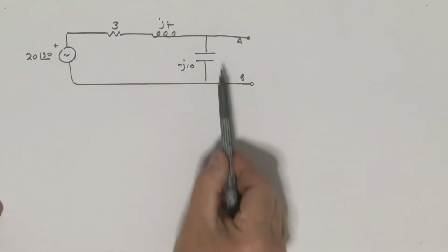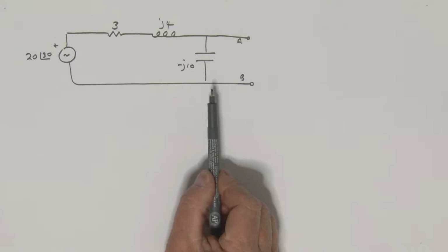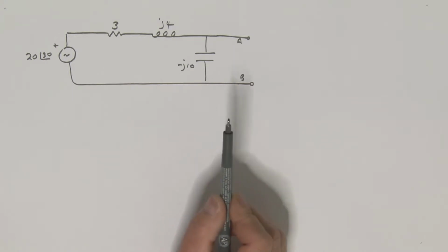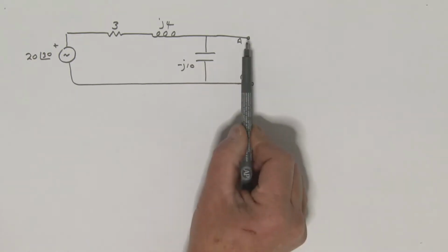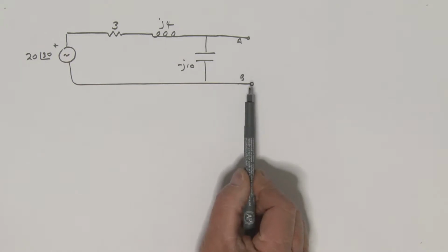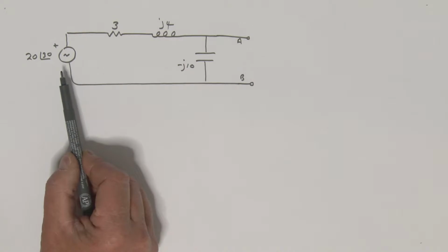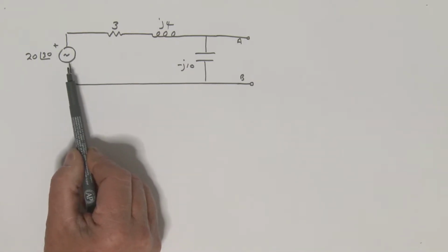Okay, you'll note that this is the same problem that we have just looked at in the previous module. And we calculated that Thevenin impedance by first finding the open circuit voltage, which was the Thevenin voltage, and then the short circuit current, and dividing that into that Thevenin voltage. Now you'll note here that we have one source in this particular problem, and it is an independent source.